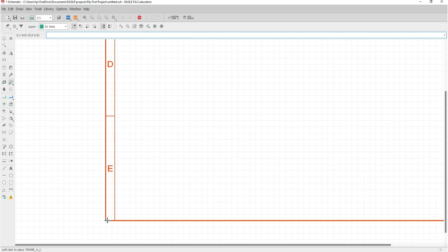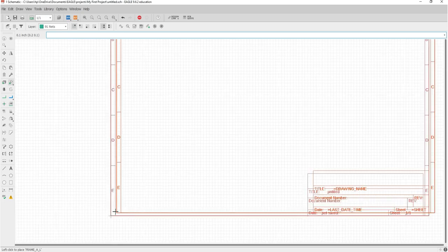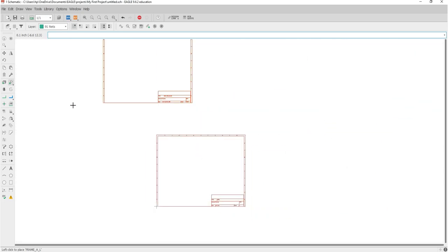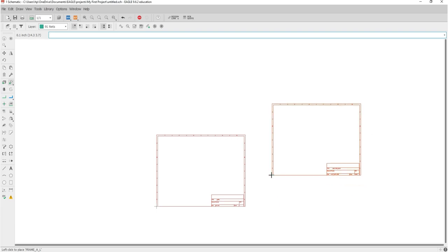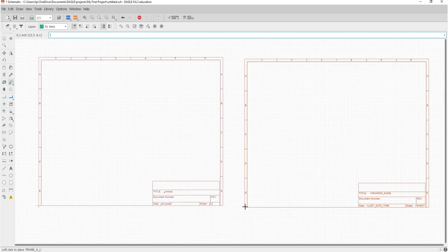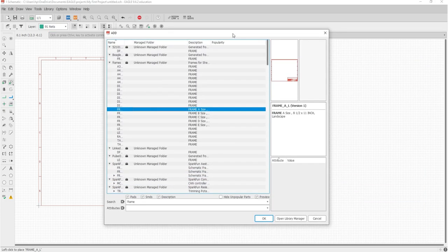It is better to place the frame on the right up side of the origin dot, so you can do your work later on the positive quadrant. Now, after you place it, you will notice that you will have another copy of frame. Since we don't need it, we can just simply press the Escape button on your keyboard. And it will lead us to the components window again for us to choose another components for the schematic design.